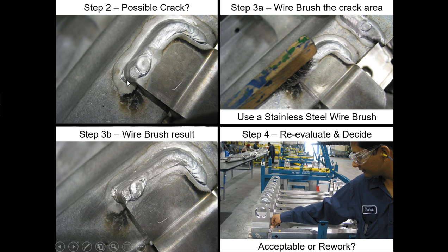And this one's very well done. And then the weld comes to the end and it actually comes back a little bit and finishes and terminates on top of the part. Now, you'll see the middle of this has got a little bit of a meniscus. It's got a little bit of a dent in it. That is typical, but it's still a sound crater condition. There's nothing wrong. In fact, that's an excellent weld, and I know it would cross section very well.